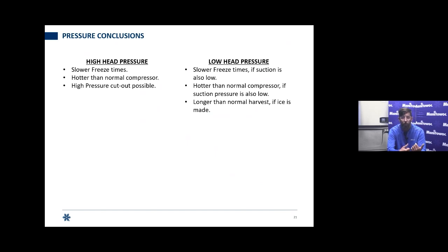So water reg valve, condenser not being plugged on the water cooled, fan motor not running, pressure switch not closing on the air cooleds, fan motor not running on the traditional remotes, fan motor and pressure switch on the CVD systems. But what about low head pressure?